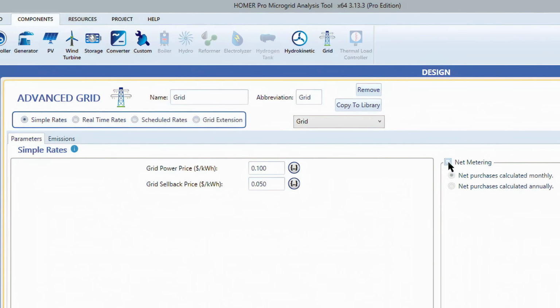And about net metering, we can also choose this part. You know that we have feed-in tariffs and net metering. Net metering systems have only one electricity counter, which considers the production and extra needed energy from the grid, and then it just gives you the final result of energy which is fed to the grid, or is bought from the grid.